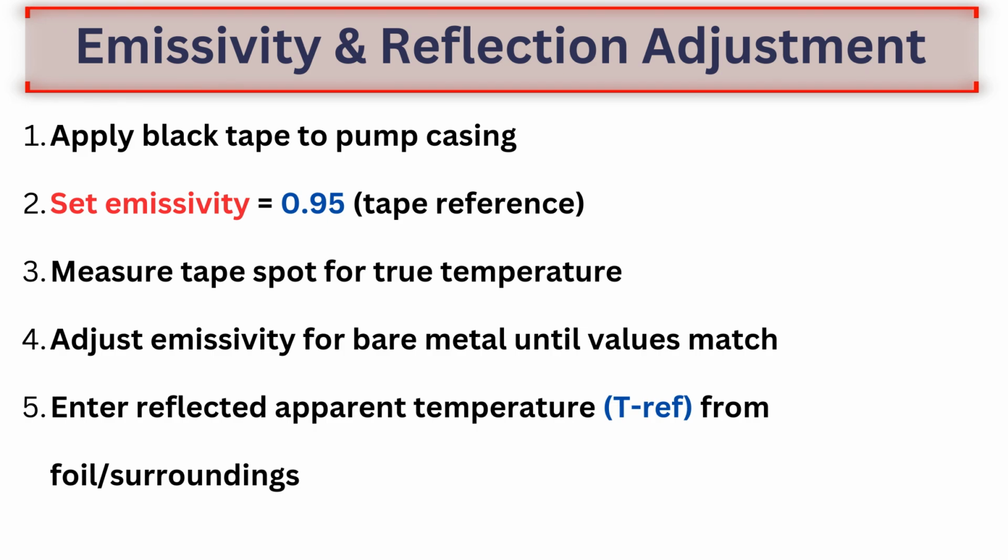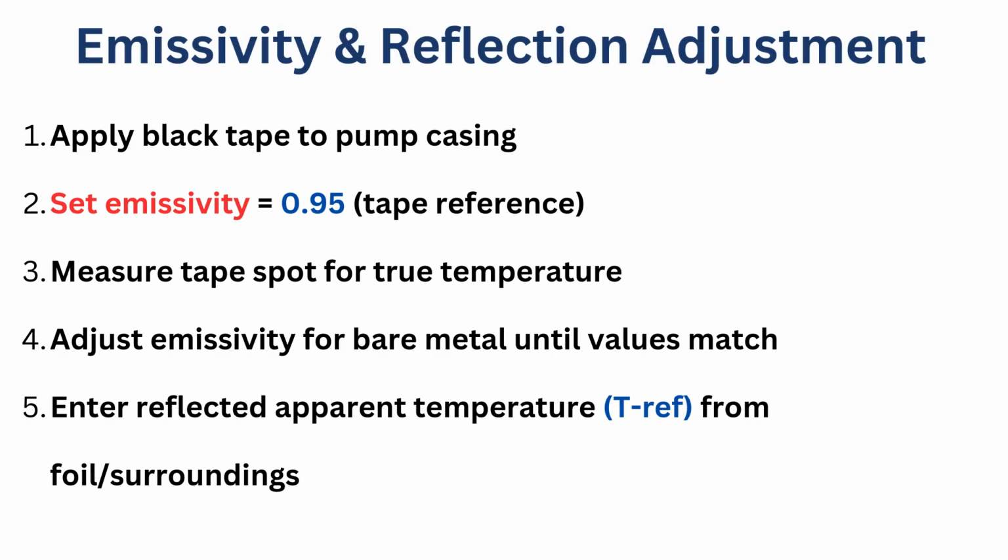If we didn't set them correctly, then 100% we are going to get very false readings. So definitely we have to have a look around the equipment, because in most cases you may find the pump has a shiny stainless steel surface, right? Especially the casing. So make sure that you know the proper emissivity of that casing.